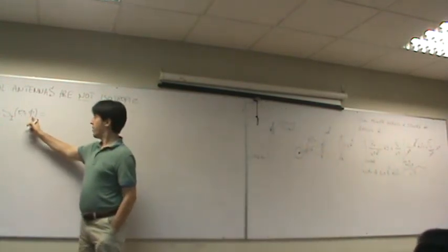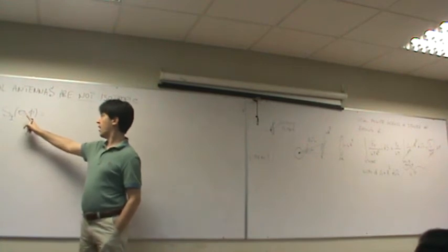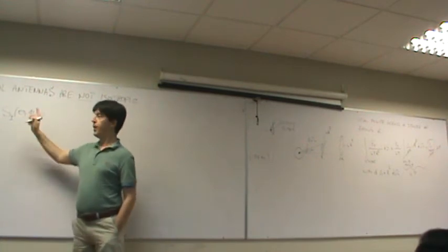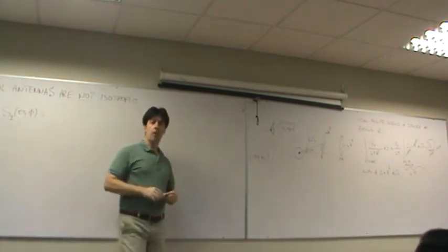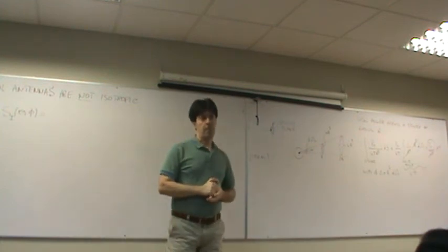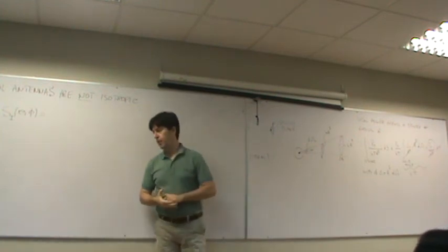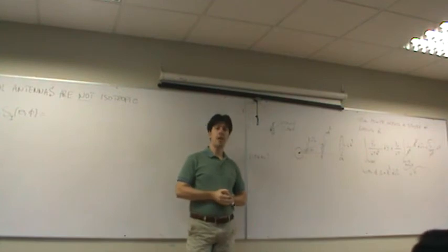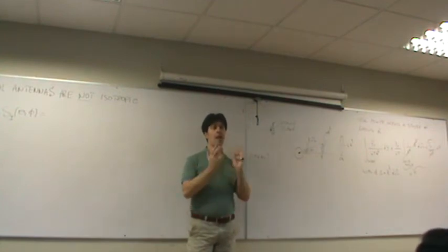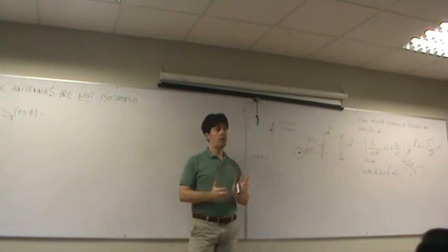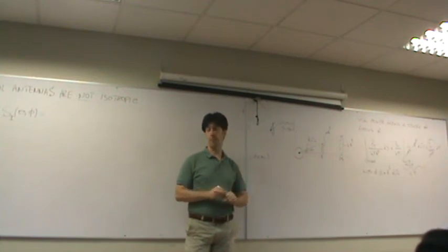Those two angles, theta and phi, are the typical angles of a polar coordinate system. It's quite important that you get familiar with the polar coordinate system because it's the natural coordinate system for antennas. Not the Cartesian rectangular one, but the polar.